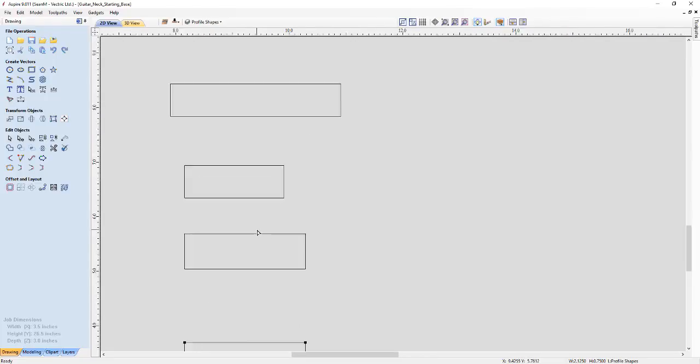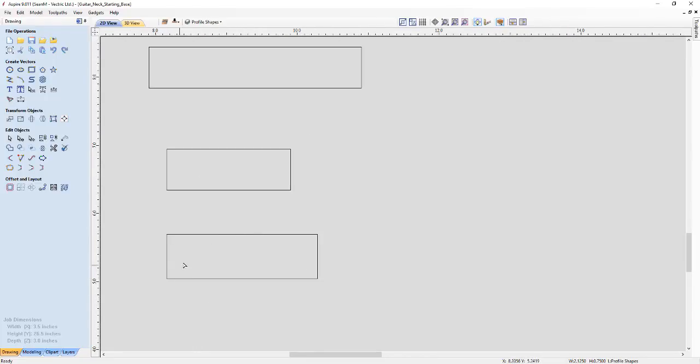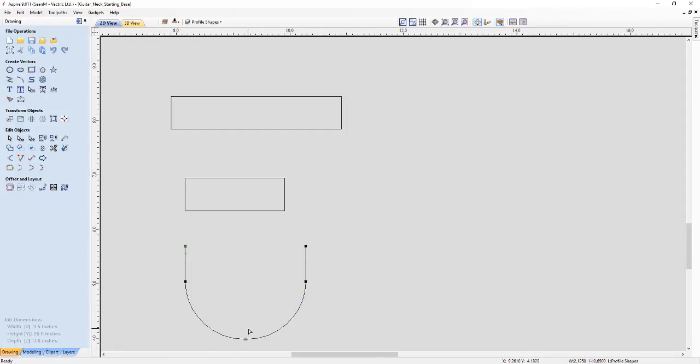Now our next one up, we're going to create an arc within that's going to basically fill this space. And how we're going to do that is we're just going to select it first. We're going to delete the top span, so just hover over again and press D on the keyboard, and then we're going to hover over this one and change this one to an arc span. Now we can either press A on the keyboard or we can right click and press to arc, like so. And see, this will jump straight out to its full extent. Now what we want to do is simply drag the control node in the center, like so, and then we want to actually just pull out and align it to the actual top node of this leg here. And this, because this is going to basically restrict the height that we're going to create our arc to.